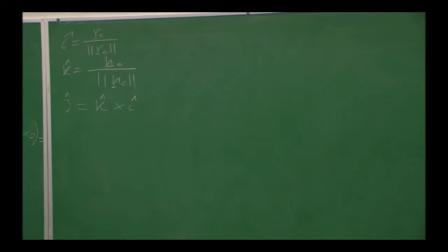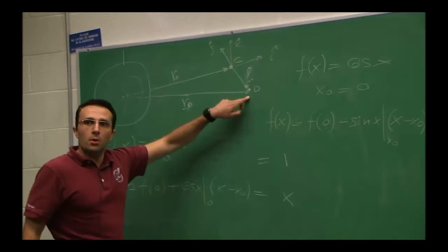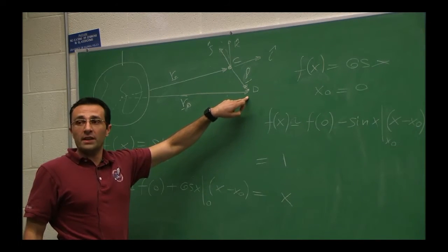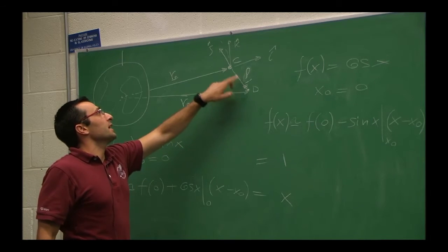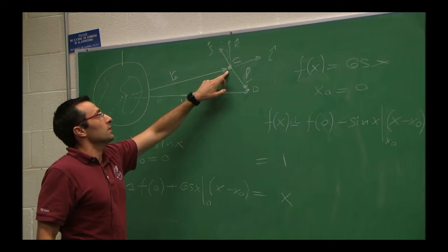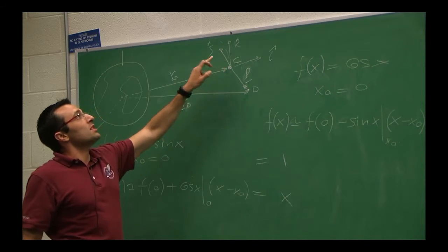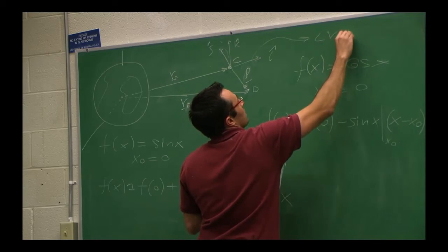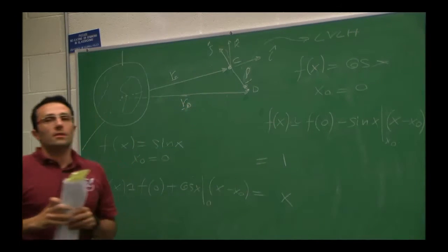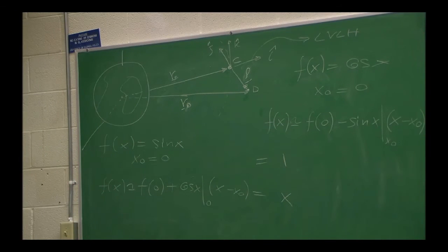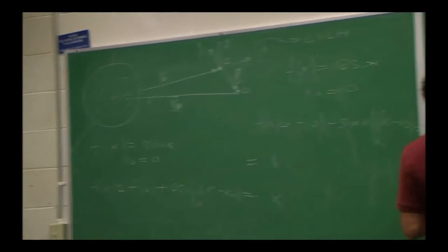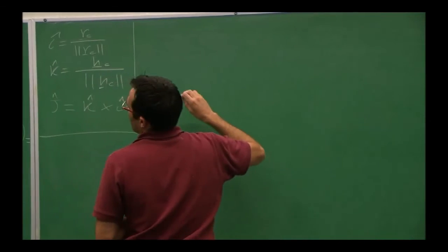What I'm going to do is write the equation of motion of this object in LVLH. All the vectors will be projected there. And then I'll linearize that equation of motion with respect to the chief. The fact that I'm using a frame that is obviously not inertial makes me expect that I'm going to use something we have seen at the very beginning of the class. What is it? Transport theorem. There's no escape.